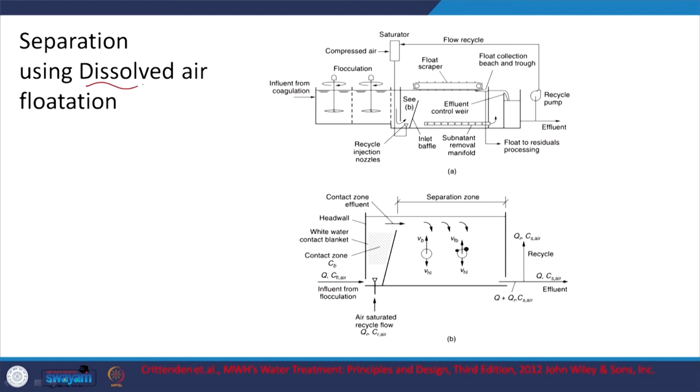And recently people have also been looking at dissolved air flotation. Well, this seems a bit counterintuitive. I want to see to it that there are quiescent conditions, stable conditions, no mixing, such that heavier particles come out. But what is this about dissolved air? Why will I pump in air? Doesn't that create an additional element here and maybe some turbulence initially?